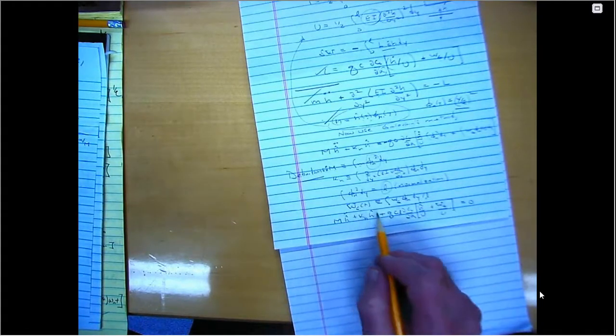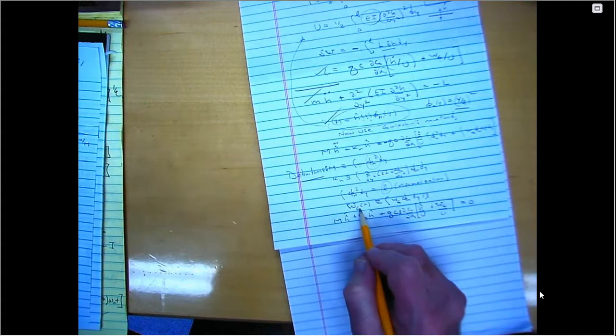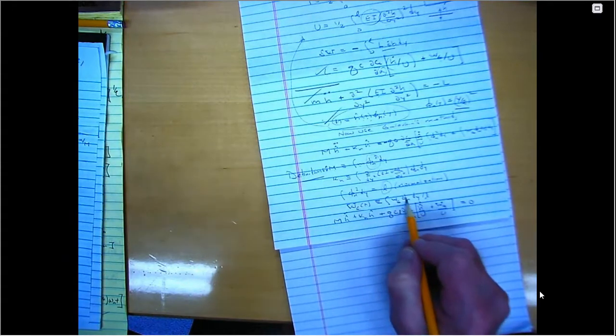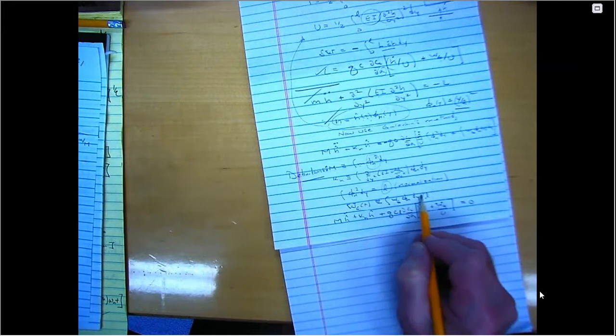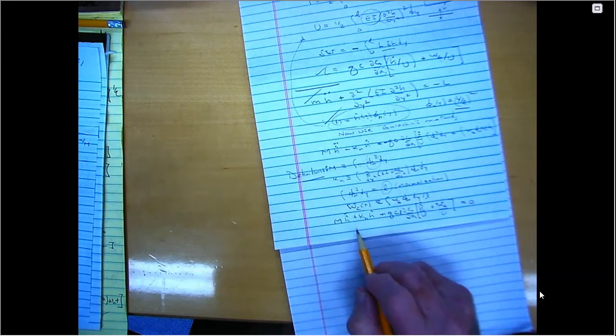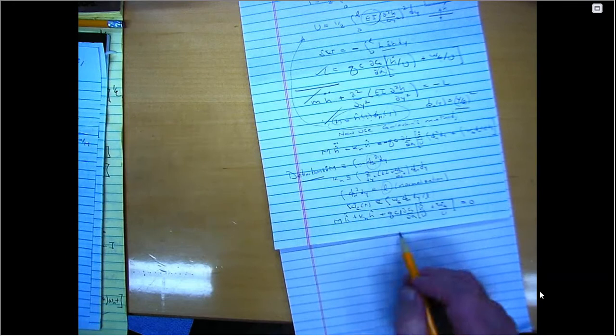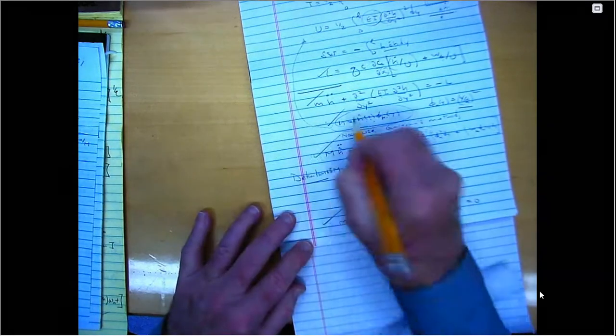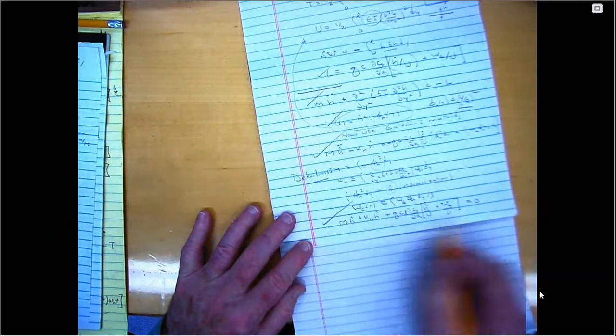And then this is, if you will, a generalized gust velocity. It's the actual gust velocity weighted by the mode shape and then divided by L to make this have the same dimensions as the gust velocity. And if I use all these definitions, then I can simplify this equation to this form, which is a standard form.